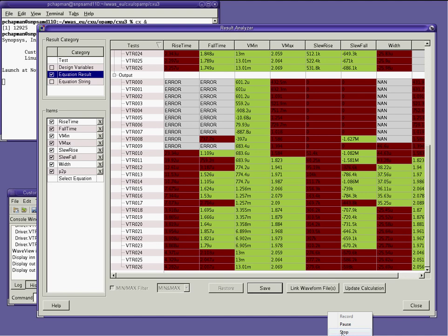However, this being analog design, of course we're not going to believe the numbers alone. What we want to be able to see is waveforms. So how do we get to those? VTR18 here. Let's have a quick look. If we select that, we can see highlighted in yellow are things where we can display a waveform from it. Easy enough to do in wave view.